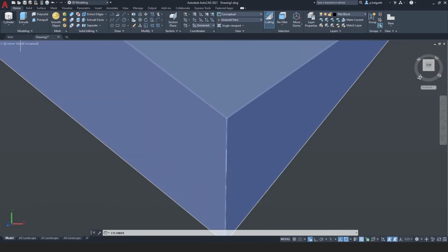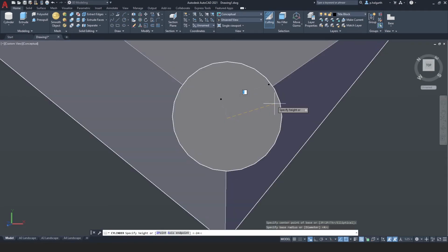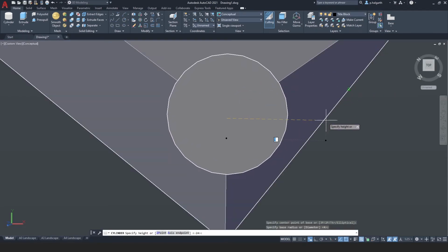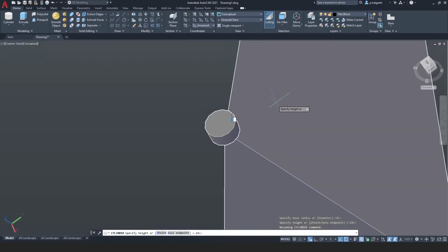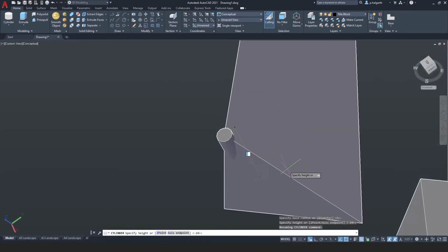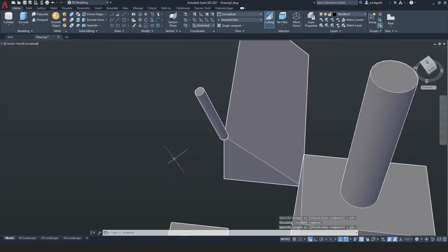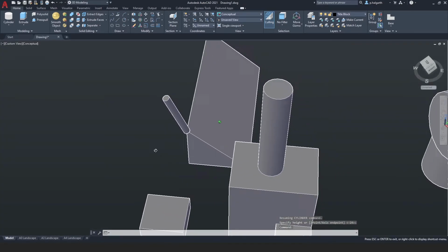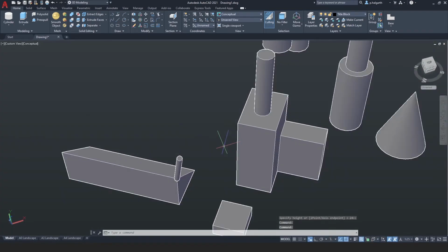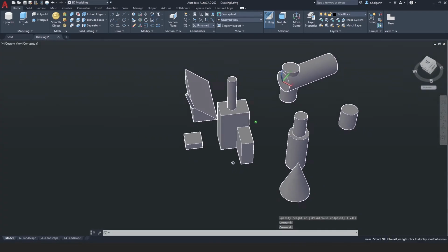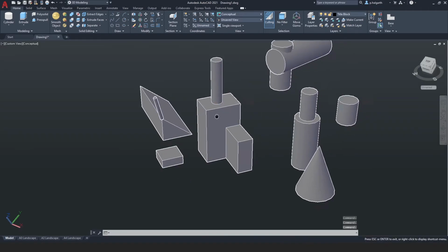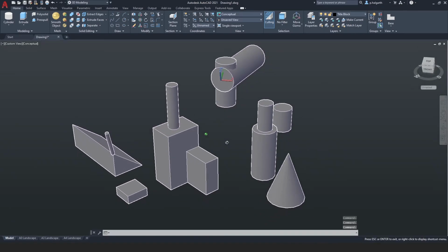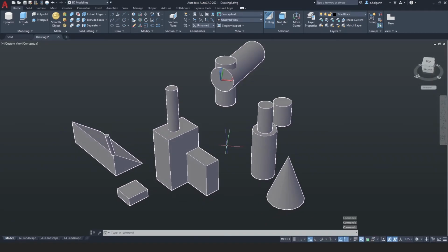So now when I pick up my cylinder, I can click in the corner there, and now I'm drawing towards me. Let me just rotate this screen around so you can see what's going on. Zoom out, and look, I'm now drawing exactly in line with where my screen was positioned. And that is a really useful trick in order to be able to draw exactly where you want in AutoCAD in a 3-dimensional world. So have a little play with that and see how you get on.